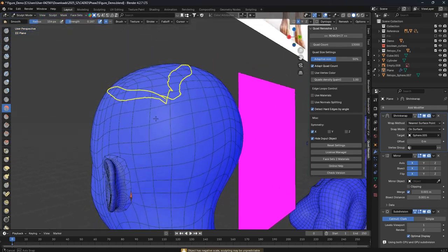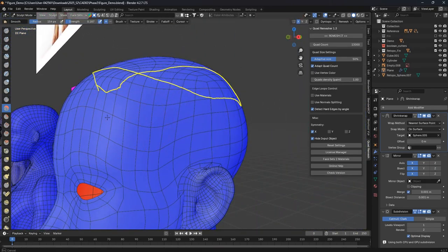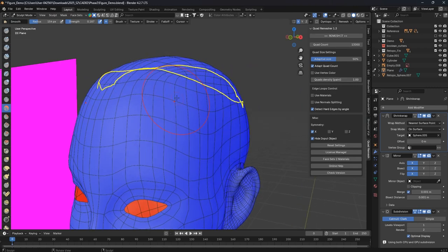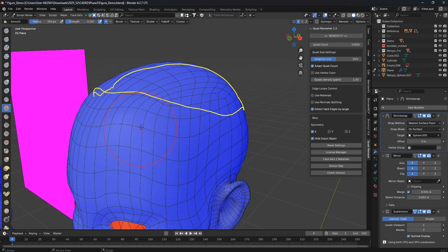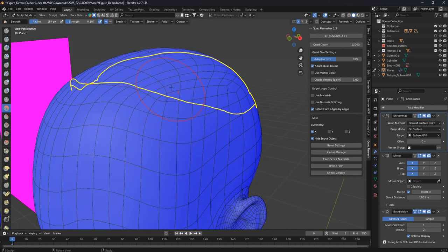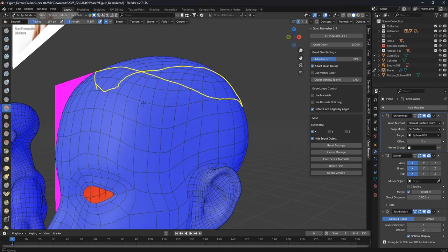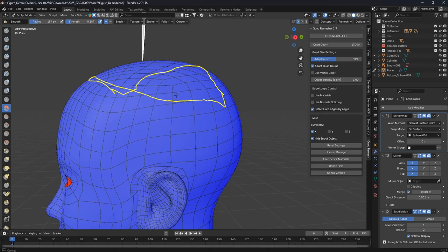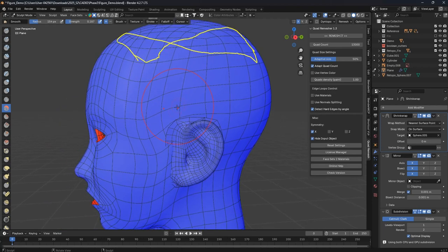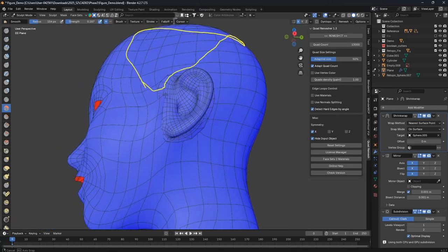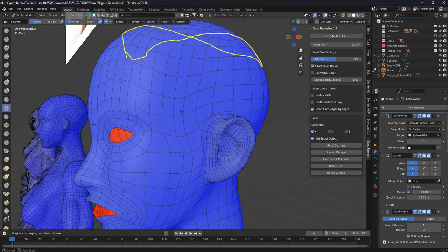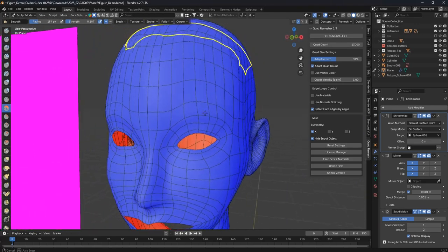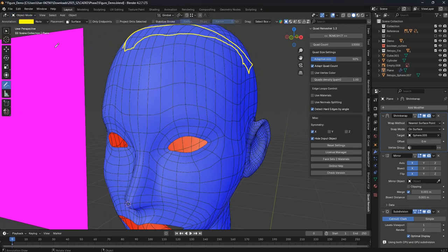And the thing I was talking about is that probably some part like this part is not that smooth at all. And usually we prefer all of them to be equal. Which means the area size, or probably the width and length of the edge for the core mesh, I hope that can be equal. So we can use the smooth brush to refine that, try to make them equal. So that's the thing. But for that part, I would say it's not completely necessary, but you can try to use this one to refine your geometry. Okay, so once we finish this part, let's keep moving forward.